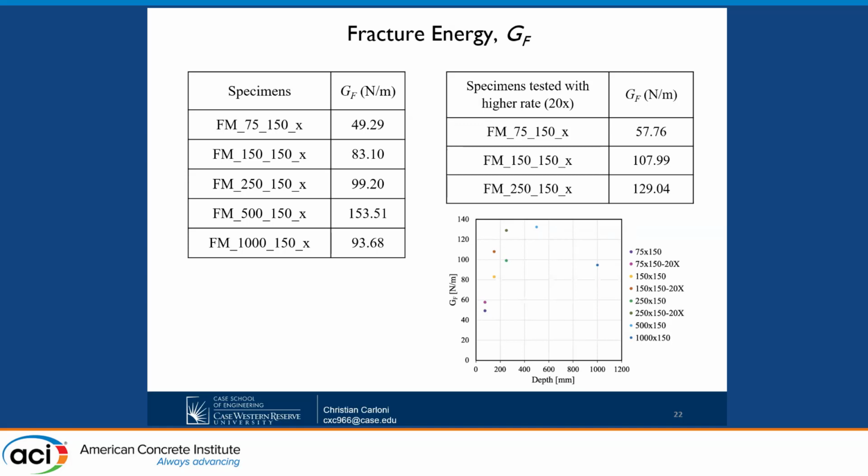That's why it's so hard to take data from the literature, because if you start to pull in data and you don't know if they were tested with a certain rate, especially old data, when there was not that habit of reporting all the details of the test, even for compression, if you test your cylinders at a higher rate, you get a higher strength. So the strength increases if you increase the rate, okay? So all things to keep in mind if you really want to compare data.